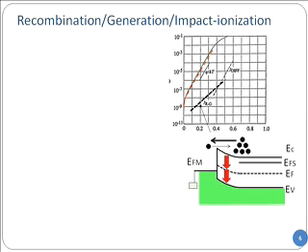Now this is something you have also done in homework, that when you have a forward bias junction, what the depletion width is, and correspondingly what is the integrated Shockley-Read-Hall recombination. So you have done this before, and that will give you a recombination-generation dominated region that has half the slope of the thermionic current region, right? Why is it? Because the electron and hole concentrations both have to balance at the point of maximum recombination. Therefore, this extra 2 in 2q over kT, that's where it comes from.